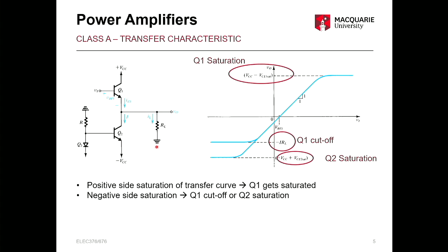So if you're drawing too much current, depending on the size of your load, on the load resistance there, that can actually create the cutoff voltage. So we went into that in a little more detail last week. We won't cover it much more today. And then your limit to get your maximum output swing for your full class A conduction angle is just this equation. So that's essentially ensuring that we're limited by Q2 saturation rather than Q1 cutoff. Make sense to everyone? Happy with class A?